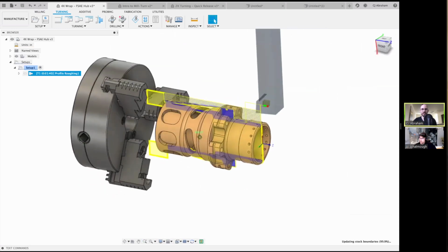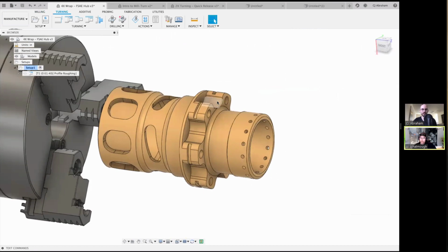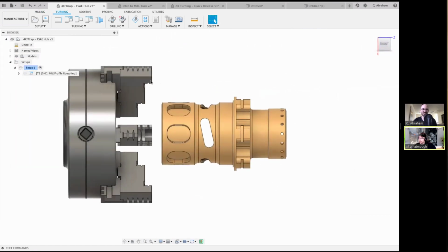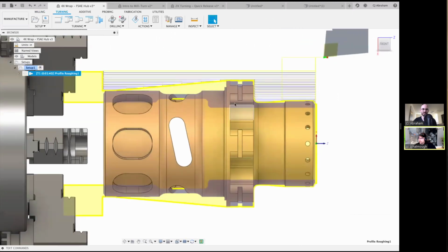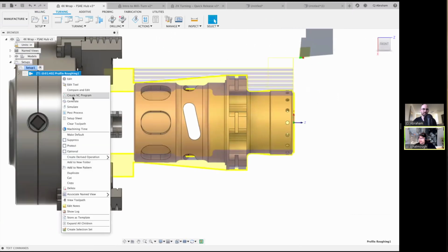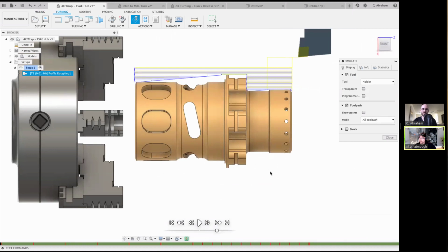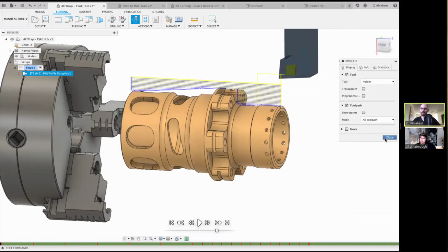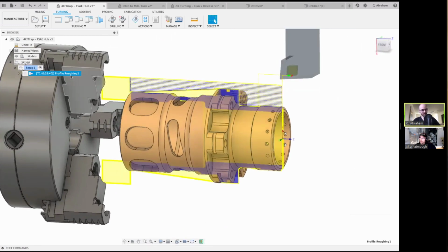And then let's say that we wanted to use... Just show that angle for a minute. I keep distracting you, but show the toolpath on the back. People might be wondering why that long angle is maintaining the clearance on the back side of the holder. If you're wondering why that toolpath may look quote unquote funny. If you didn't want that to happen, how would you stop it? Oh, well, let's use tangential extension.